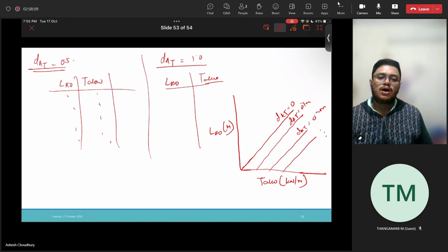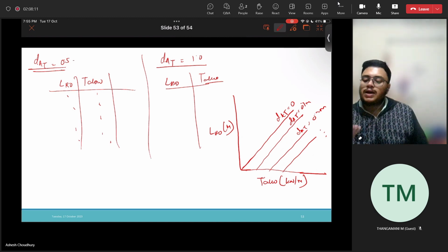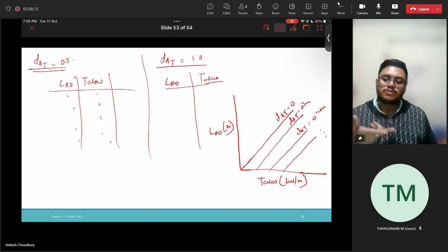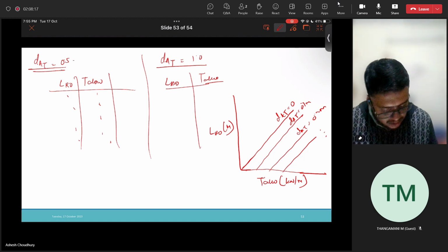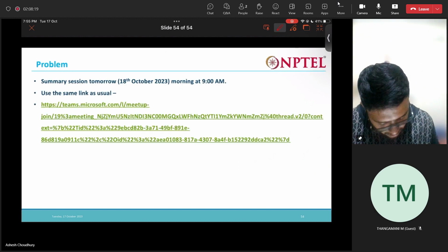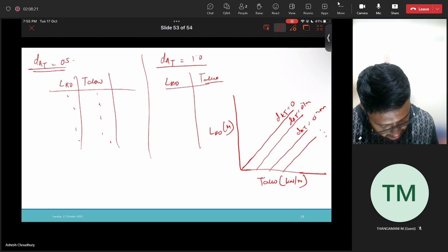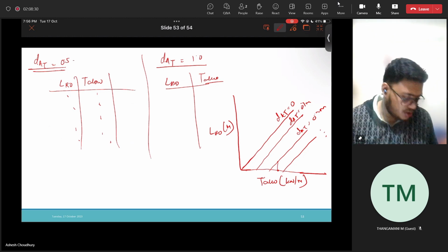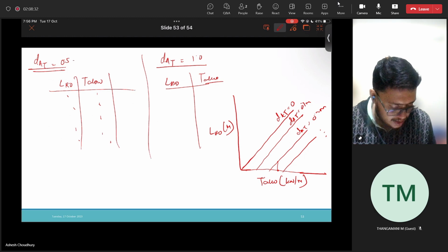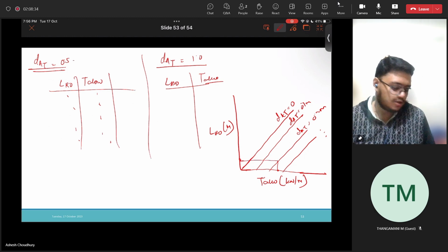Say now you know that you have to use this geomembrane, and this geomembrane has an allowable stress of this much. You just go to the chart. My geomembrane has this much T allowable. For that, if I choose a depth of 0.2, I have to use a runout length of this much.